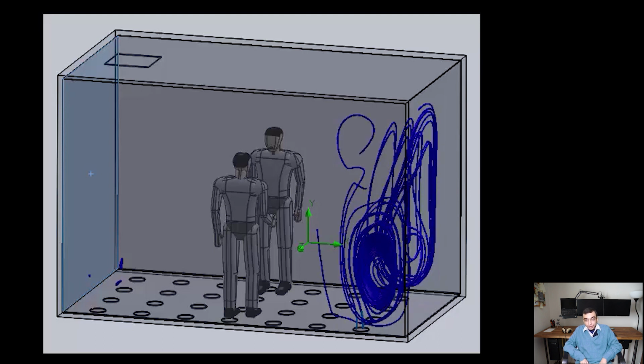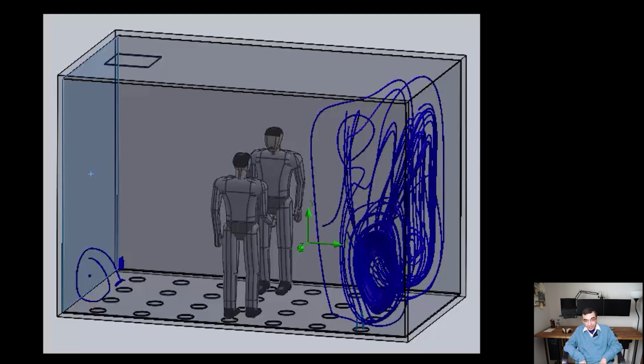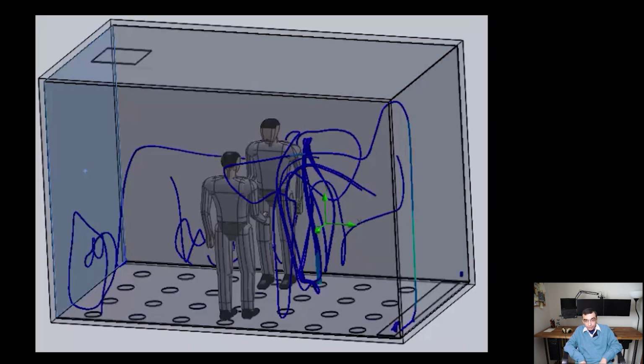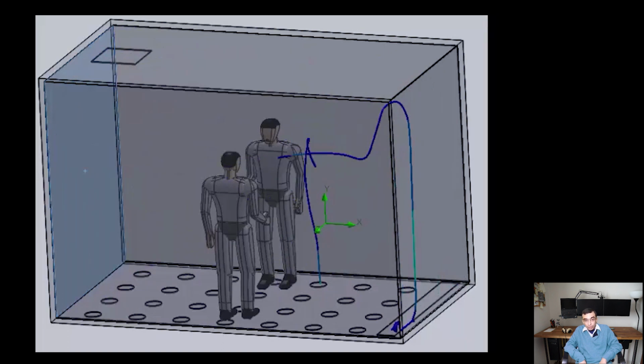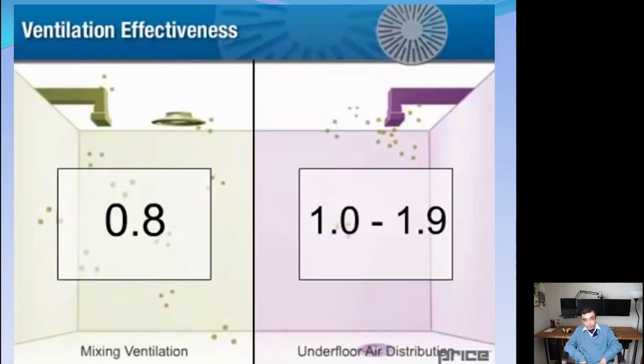The system works for each individual, like the drip irrigation. Flexibility in the room activity. Window air barriers are used to reduce the effect of the outside heat. Lower air velocity, no mixing issues. Minimizing the conditioned air volume gives warmer supply temperature. Higher ventilation effectiveness due to the low level of the supply and the high level of the return.